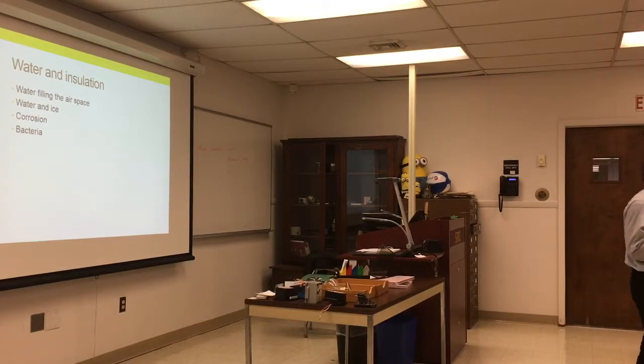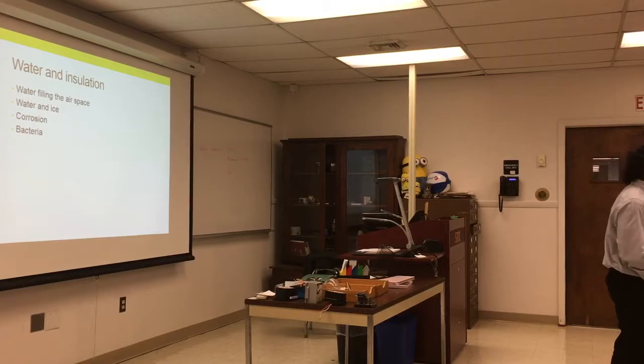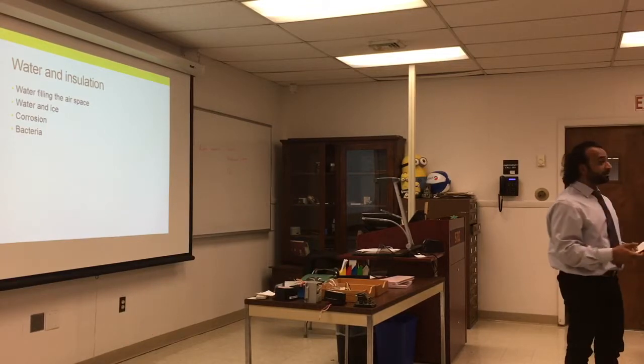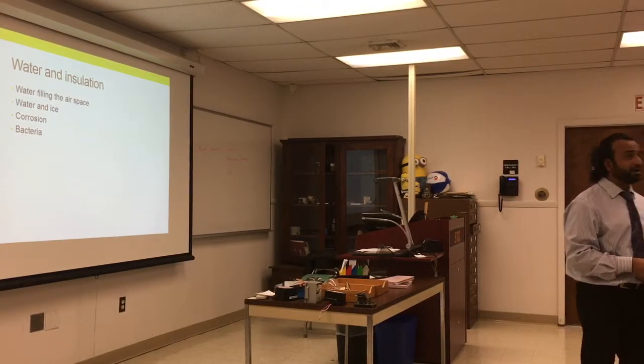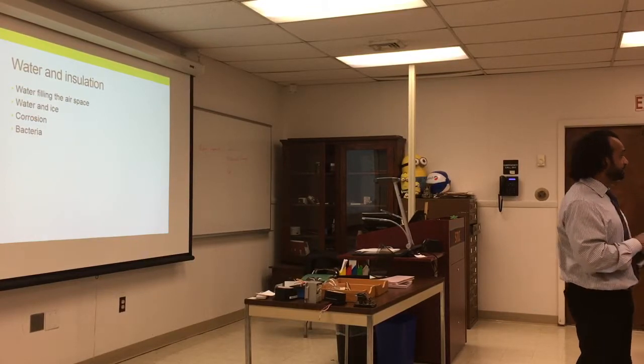Usually the basement is made out of what? Concrete walls, usually. Concrete is not completely insulated unless you put some barriers in it. So eventually it will be moist. If you touch it, it's kind of moist. We say concrete is never 100% dry. After 100 years the core of it is still moist.